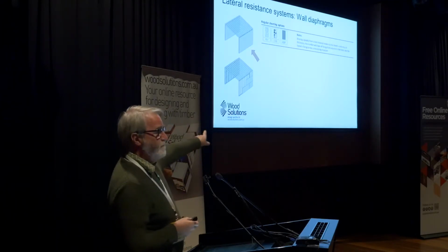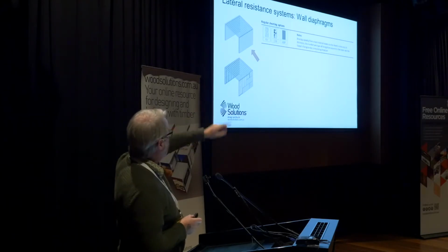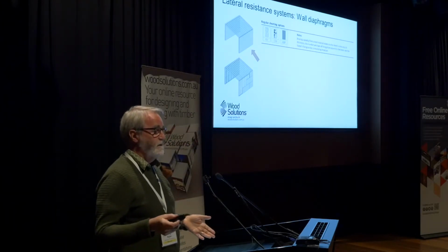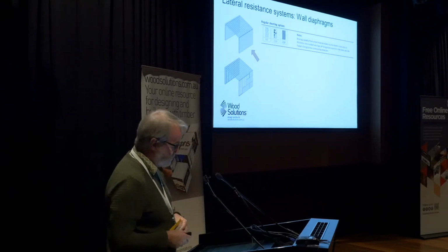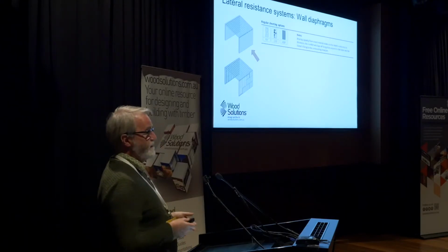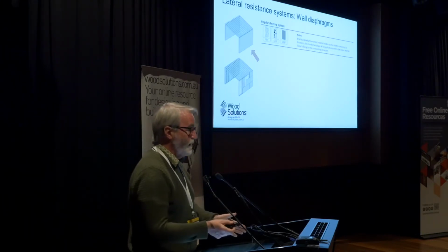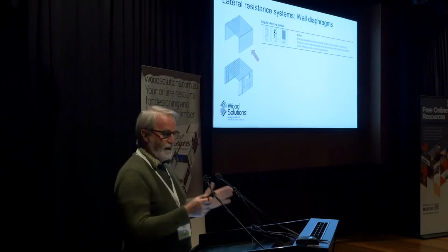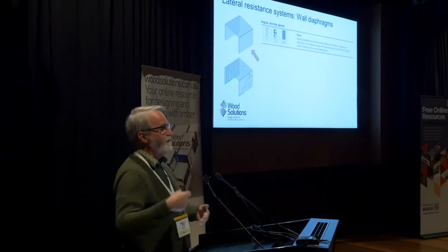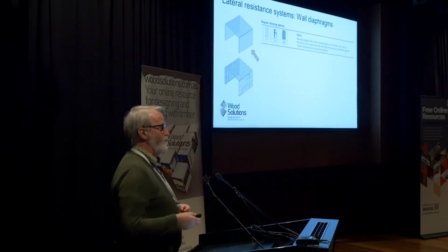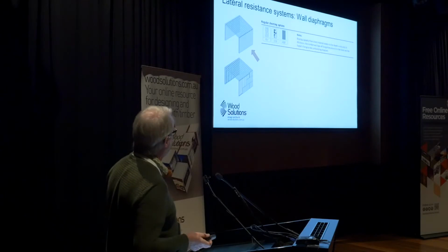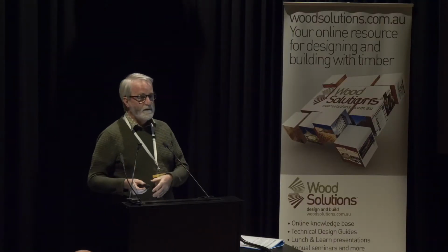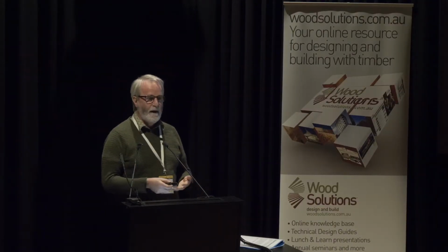Though if we've got a stud frame wall system, we can see there that we can sheet it in a whole range of different materials that will enable us to get particular load capacity into those wall systems. We don't go down to the detail where we can say you're getting this load capacity. We're going to say here are your options. You then can develop it up further to work out what loads you've got to resist and the different materials and fixings, etc. you need to do that. So there are various ways you can join bits of wood together, and how you join them is going to impact your aesthetics in your structure.